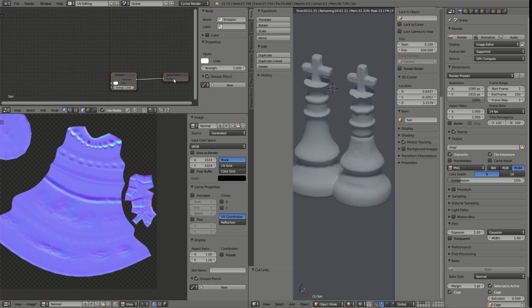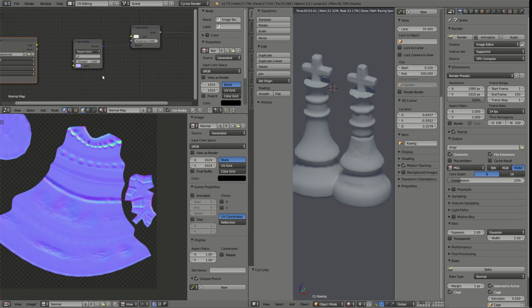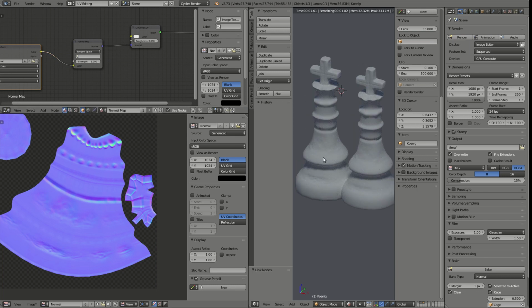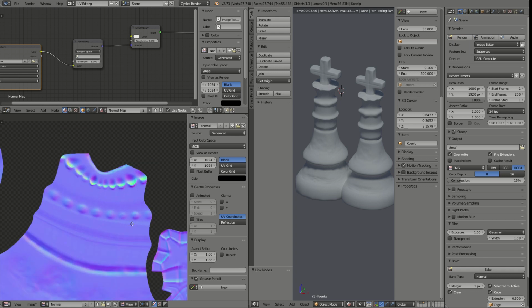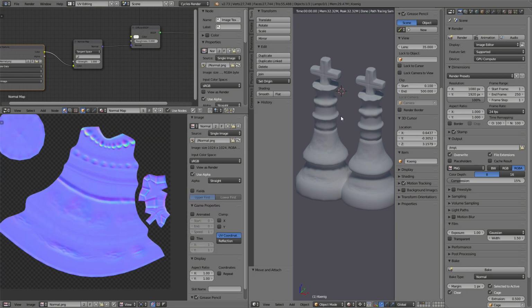Yep. And here to the left, let me simply show you it once again, adding the normal here, color here, and now they are very similar. And that's basically because it's the shading. The normal map will change the shading based on the pixel color here, and of course red is X, green is Y, and blue is Z. So the color information pretends that each shading point, which is basically sort of a pixel on a 3D object, has its own normal.